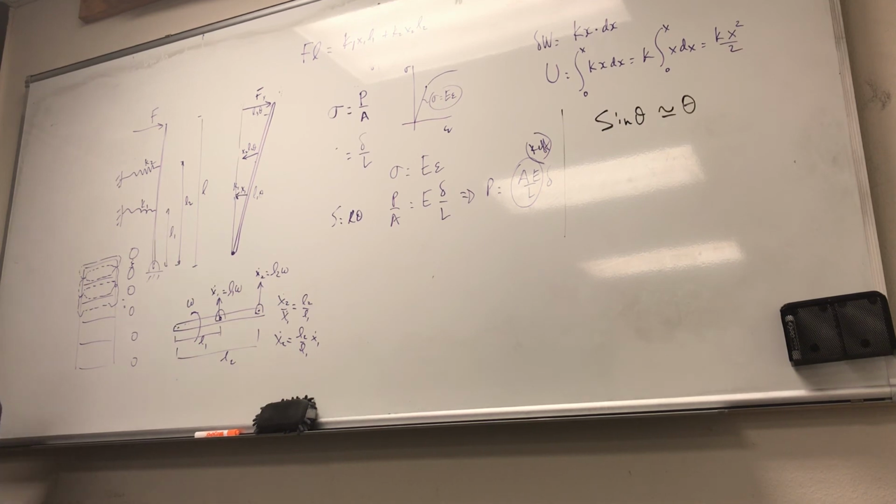Then you only have the mass equivalent equal to something. Okay, so there you go. So that's how you combine masses. Remember, the only thing you need to remember is that the criteria has to be the sum of the kinetic energies of the individual masses has to equal the kinetic energy of the combined one.